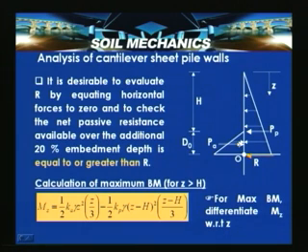So, maximum bending moment is calculated for this simple active case for a cantilever sheet pile wall by using this method. The calculation of the maximum bending moment, that is for the Z value greater than H, is assumed to occur below the dredge level.